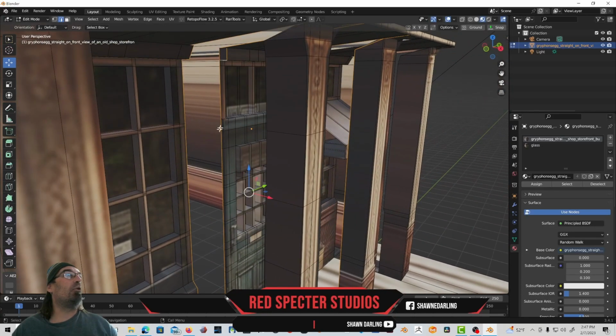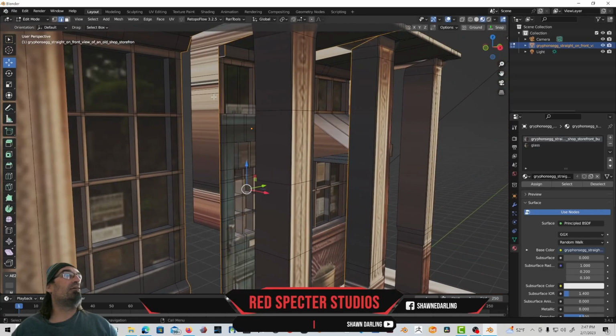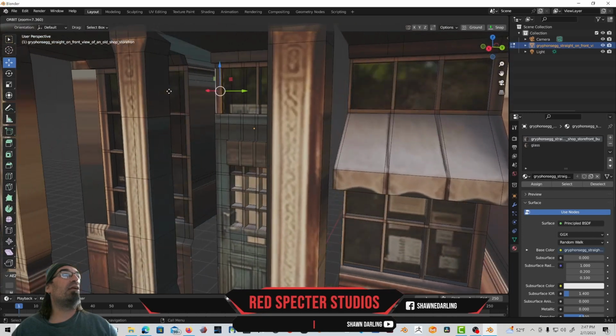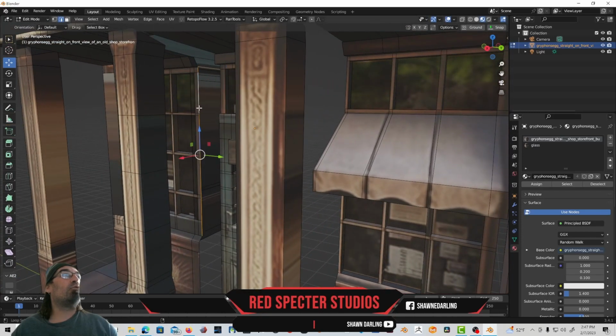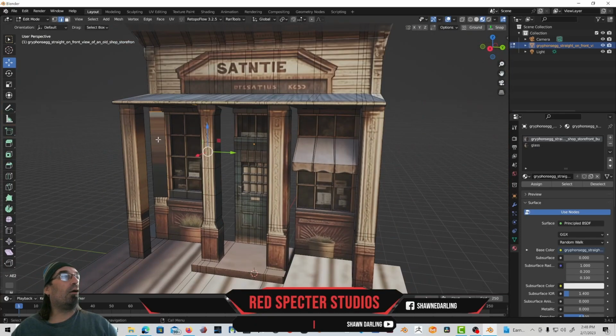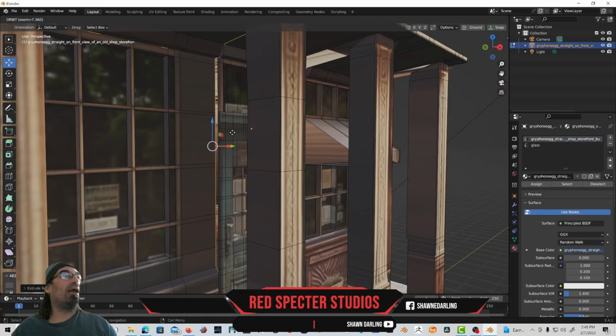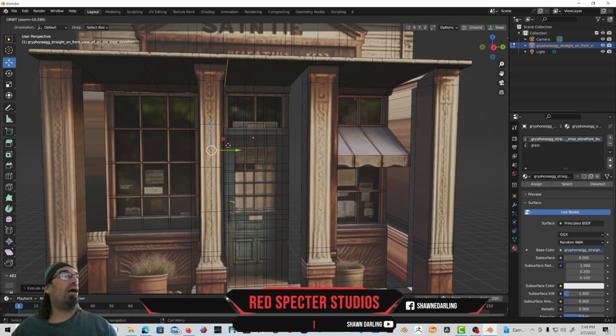And this is because the door has broken that up so much it doesn't just coincide and come across that nicely. So I'm going to try and get rid of these selections I made here. Let me just reselect this side, including those. And now we're just going to extrude along the Y, E Y, move that over to hide that gap instead of truly close it. We're just hiding it.